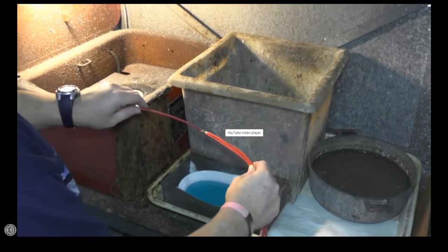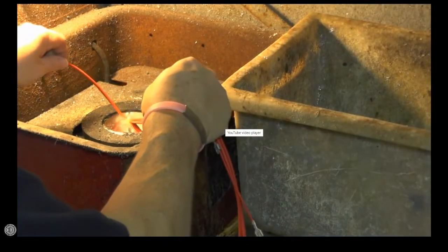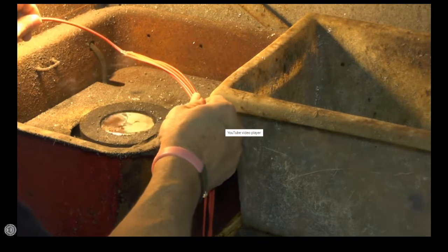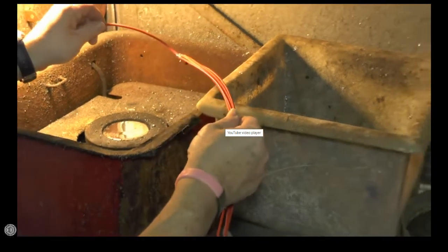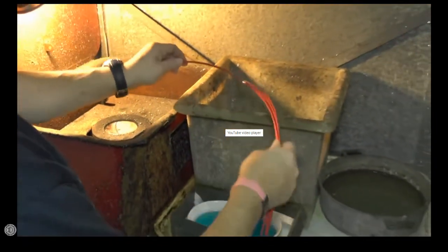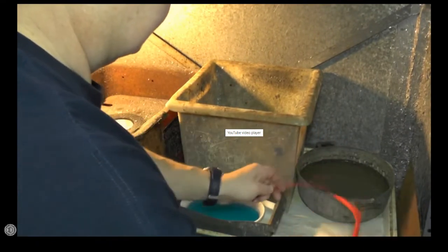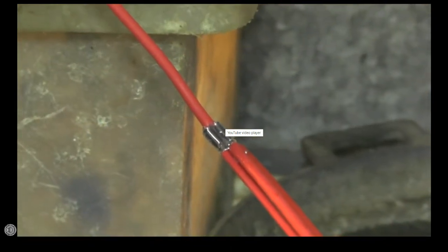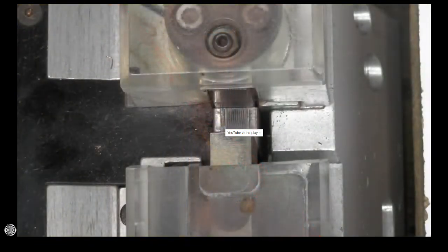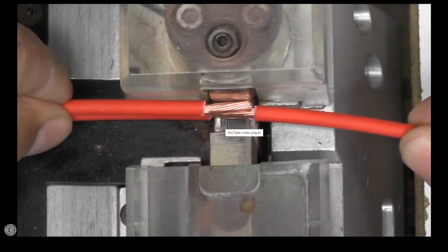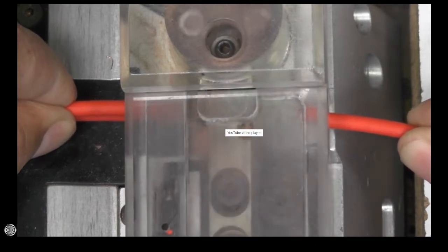There, the splice was first dipped into a cleaning solution to remove oils and oxidation, which would otherwise hamper the solder from adhering to the splice. Next, the splice was dipped into molten solder, shaken to remove the extra solder, and cooled in a neutralizer. This was the splice method that manufacturers used for years. The negatives to dip soldering is the possible introduction of acid and limited quality control. The splice method used today in automotive wiring harness manufacturing is ultrasonic welding, as shown here.